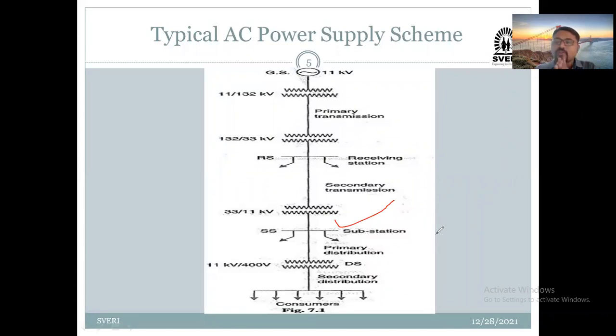What they want to say is that whatever this 11 kilovolt is, we are going to give the 11 kilovolt feeder or line directly to that particular premises, because they require more themselves. We distribute the electricity from this 11 kilovolt to that premises, where they have their own distribution station, where they can step it down and distribute their electricity to their different departments.